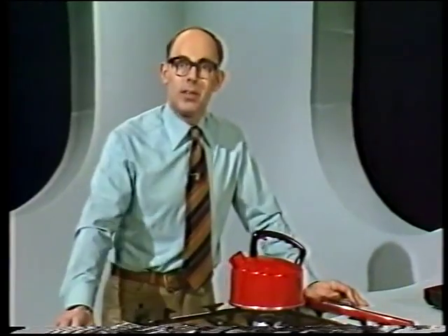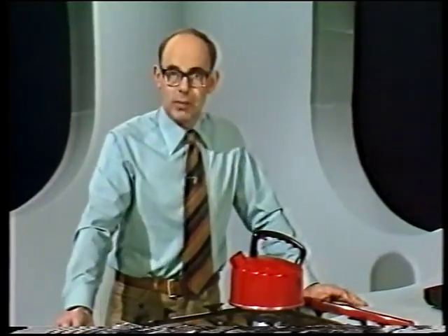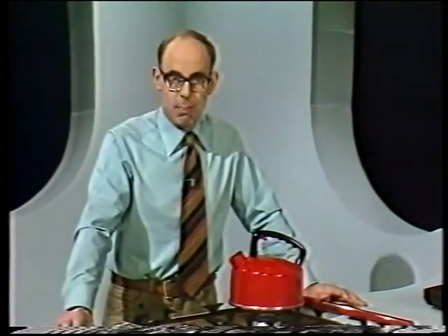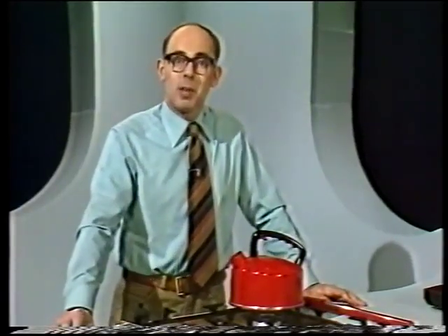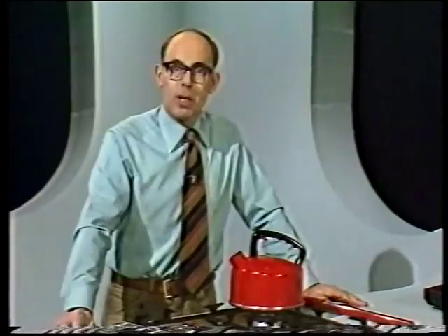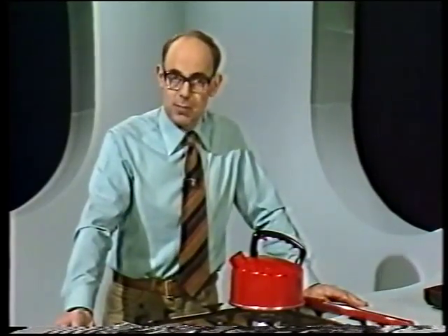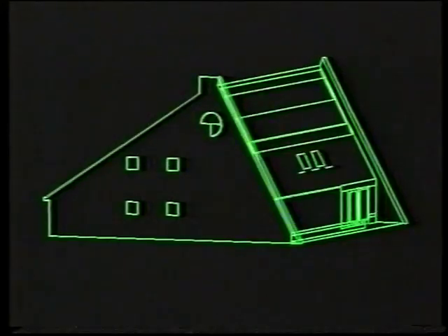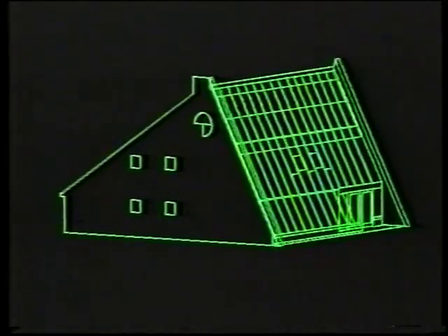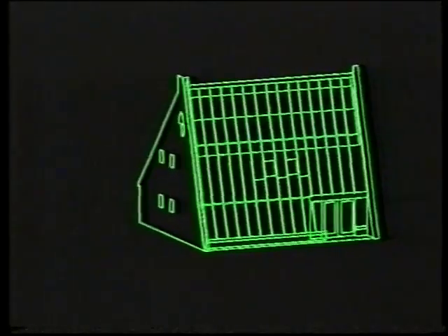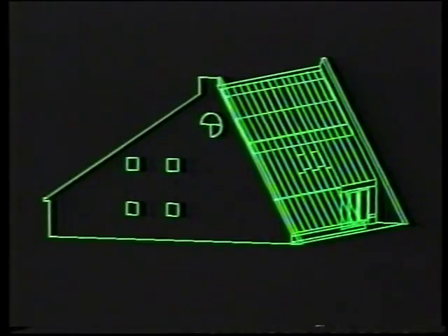You should get used to the idea that thermodynamic system boundaries don't necessarily coincide with the walls of physical objects. However, having said that, it's certainly true that whenever we try to describe the thermodynamic properties of practical systems, the system boundary frequently does lie along some physical surface. Take a familiar object like a house. To describe the overall thermal properties of this house, we could define a boundary lying on the outside of the walls and roof. The energy inputs would be thermal energy as radiation from the sun, plus any work energy taken from the main supply. The energy output would be the thermal energy transferred from the inside to the outside environment.